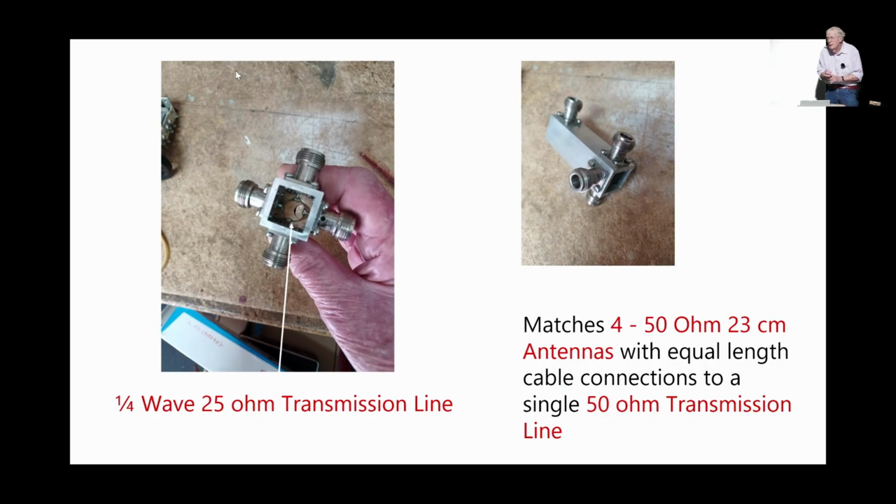And of course, you can have conductors within conductors of various shapes, and that generates various impedance transmission lines. So I was just very lucky that a lump of copper from the hobby shop was exactly the right diameter, and that extrusion of aluminium worked out fine. And yeah, the match there is very, very good. It's very close to being exactly right.